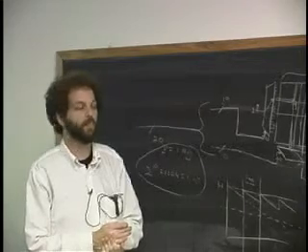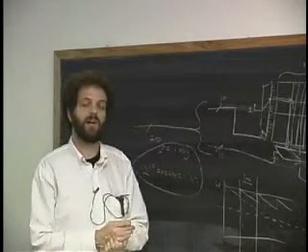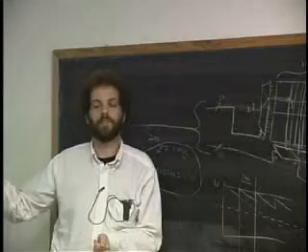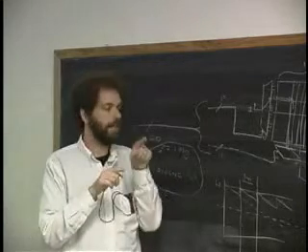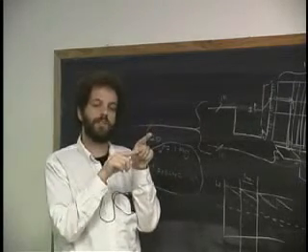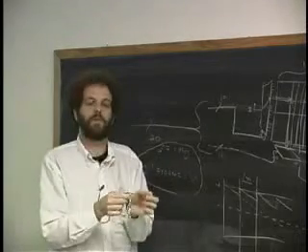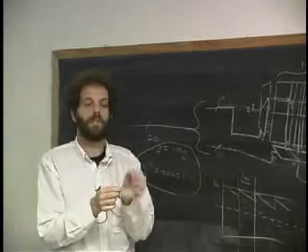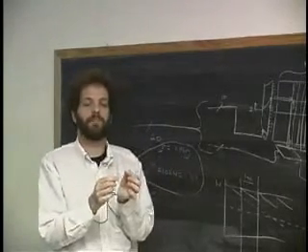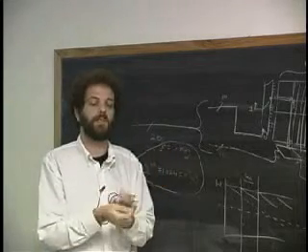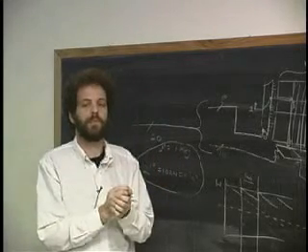Sometimes, in fact, in the old days, this problem was so hard that they wasted half of the lines. Whenever they had high charge in one, they'd put low charge in the other. They'd suck down on both of them and look for the difference, so whatever effect happened to one would happen on the other. You throw away half the bits, but you sense what the difference was between one and the other.